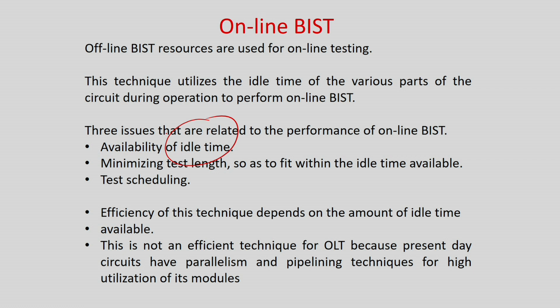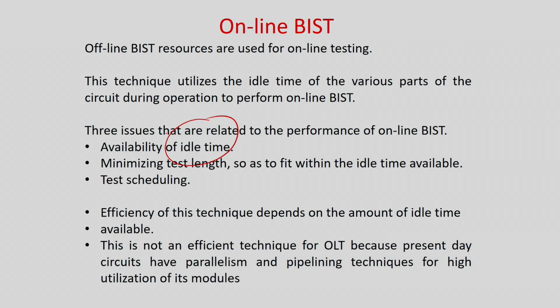Input can be stopped only if the circuit is idle by its own nature, that is, given an application, the application is running, but for a certain time the circuit is not doing any work. I am not stopping the normal inputs from coming, but because of the application which is running, it is idle for some amount of time, and quickly you do the BIST during that time. So it totally depends on the idle time, and therefore if the idle time is very less, the BIST will not be very successful.